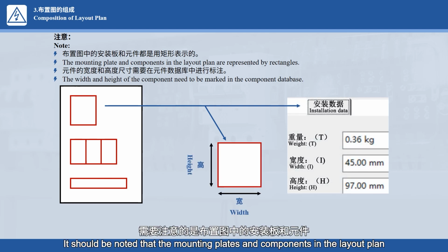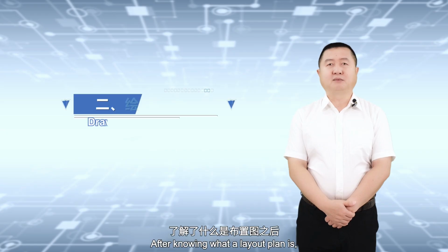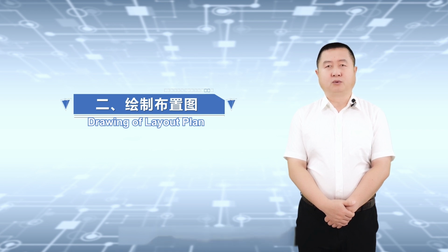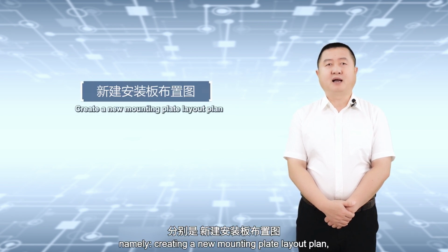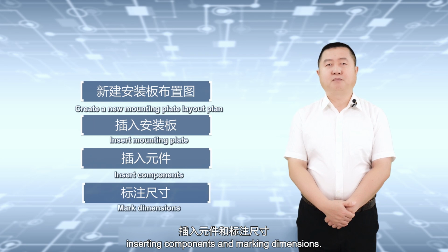It should be noted that the mounting plates and components in the layout plan are represented by rectangles. The width and height dimensions of the component need to be marked in the component database. After knowing what a layout plan is, let's focus on how to draw it. There are 4 main steps for drawing the layout plan, namely, creating a new mounting plate layout plan, inserting a mounting plate, inserting components, and marking dimensions.